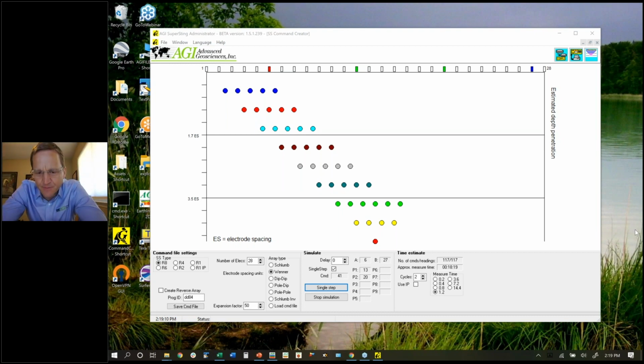What will the maximum subsurface penetration depth be if we use 20 electrodes using a dipole-dipole arrangement for an IP survey? Okay, that's a little bit off topic, but it does relate to electrical methods in general, in that for a single line, your exploration depth for these types of arrays is generally 15 to close to 20% of the line length.